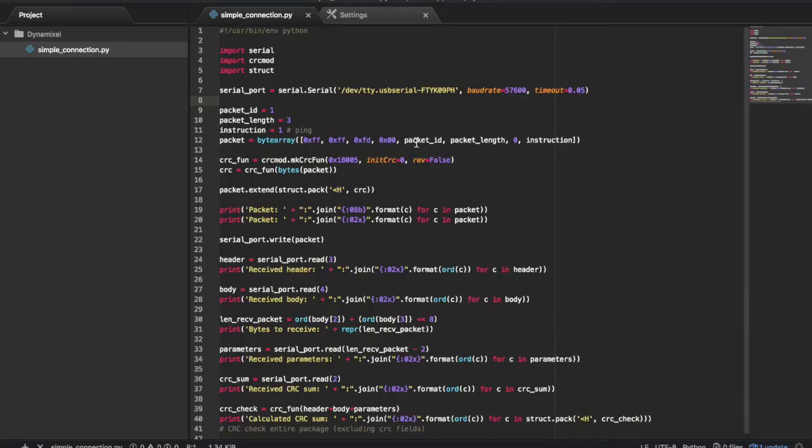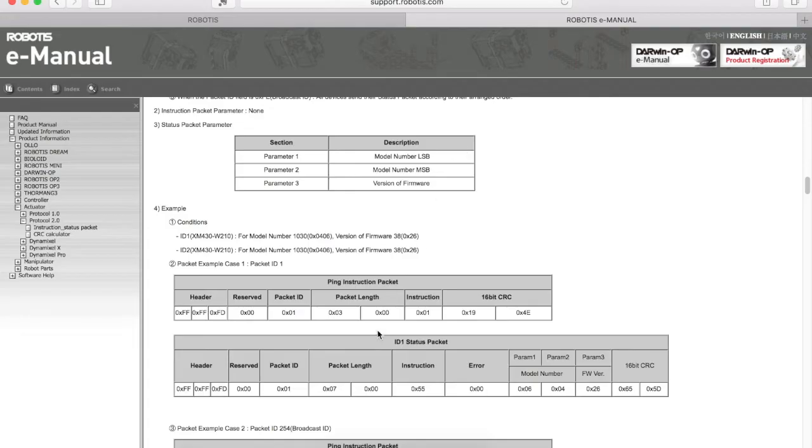Then we need to put in the packet ID and then the packet length. The packet length is divided over 2 bytes, the lowest byte and the highest byte. That is counterintuitive, that you would get the lowest first and then the highest. But remember, as you're sending it over the network, you're actually sending it from the beginning. So the receiver will receive first FF, FD, and so on. So it makes sense that it will receive the lowest portion first and then the highest portion.